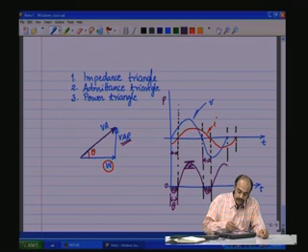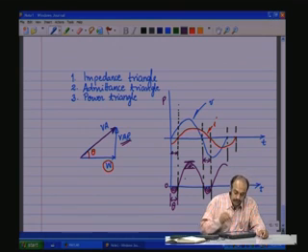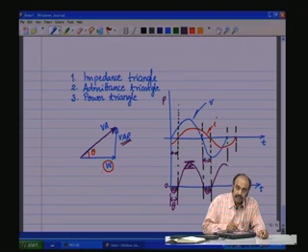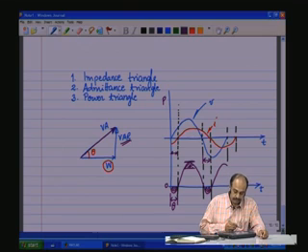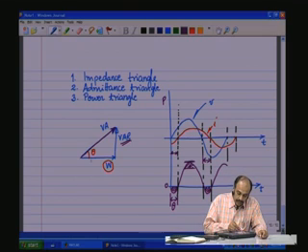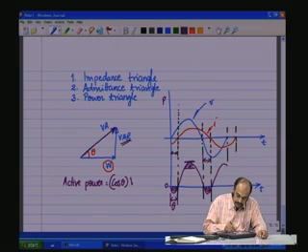The other extreme, when theta is 0, which means when the current is in phase with the voltage, power is always positive, which means everything goes to the load, and that is the active component. Nothing is put back to the mains. So, VAR will be equal to 0. So, the active power is cos theta into VA.